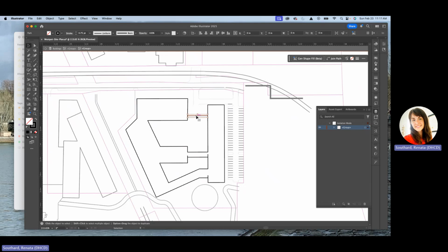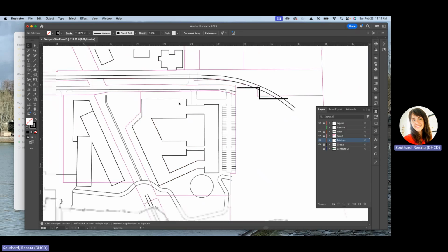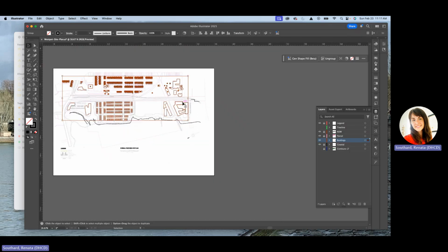And I'm inside the shape and I'm gonna use that rectangle tool to draw this again. And I'm gonna hit Command A. That's gonna select everything here. And then I'm gonna use that shape builder tool again, see how there's all one shape. Now I've got this in there too. Okay, so that's fixed. Now I'm back out. I hit escape, and I'm gonna use this again. And you see how that one got fixed.